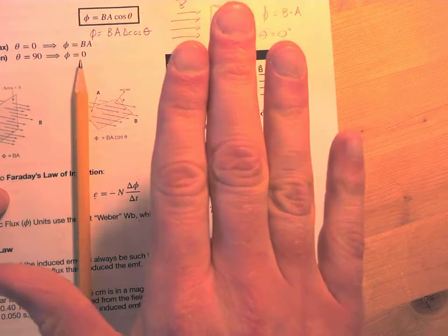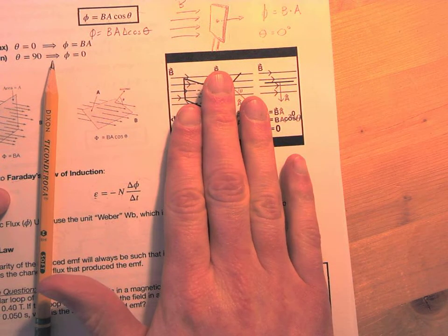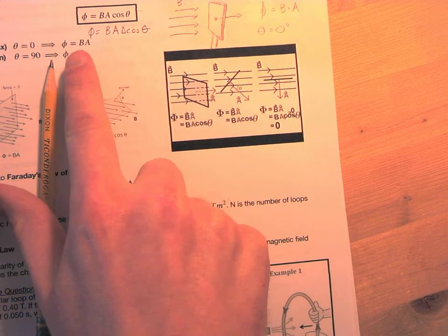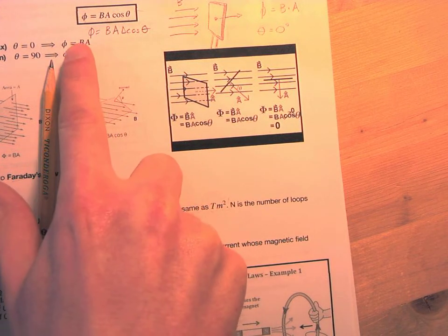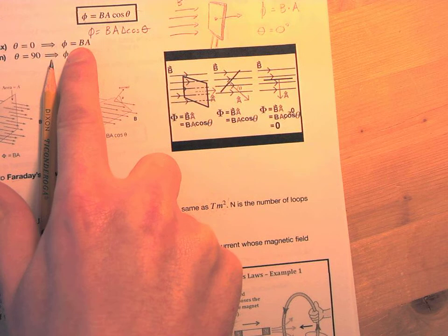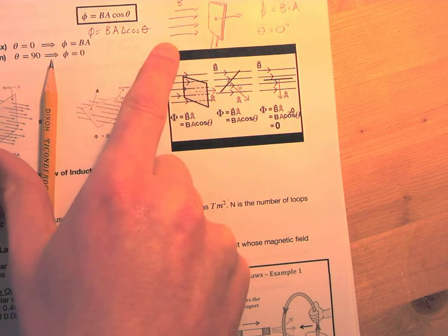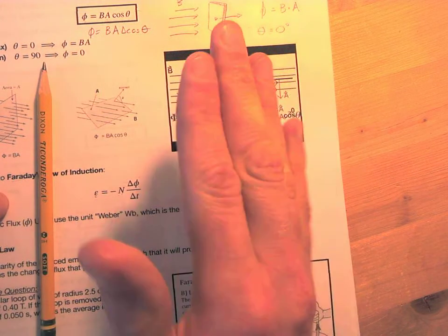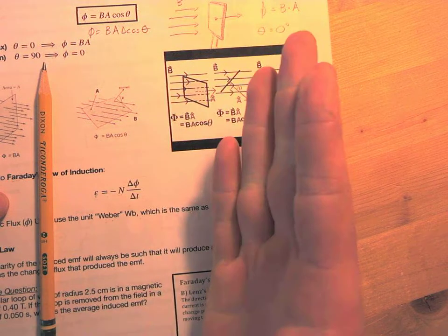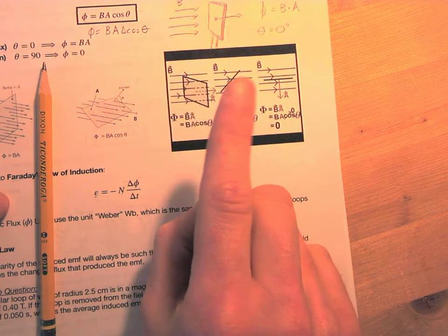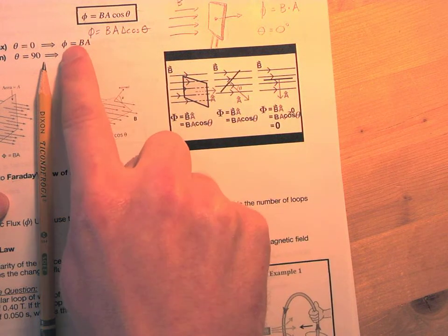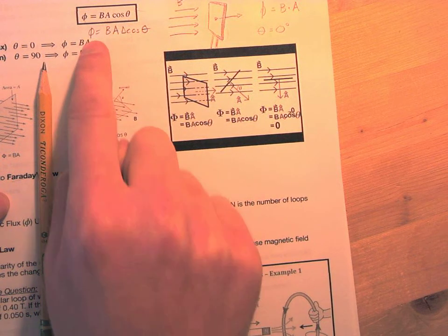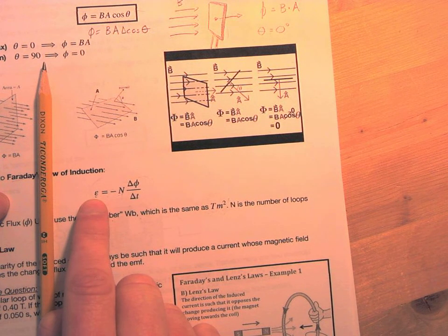But another way is, say if you had your plane in there and you weren't moving the armature, you just left it still. If you decided, or you were able to change the B value, or the magnetic field itself, then you'd be changing the flux as well. So you don't necessarily have to move the armature. That's usually what we talk about. But you can also just turn on and off a magnet, or say an electromagnet, and that would change your B value really quickly, which would change your flux, which would change your voltage.